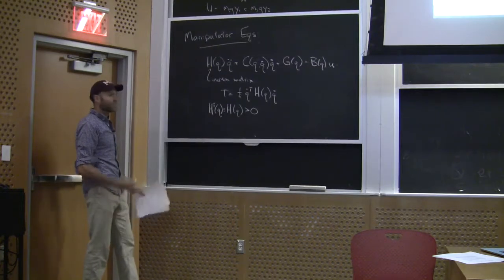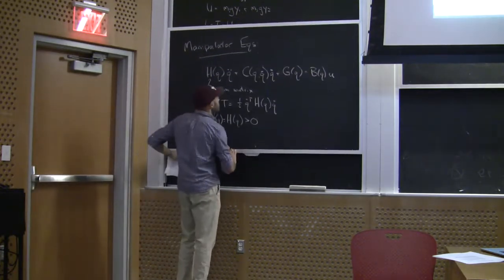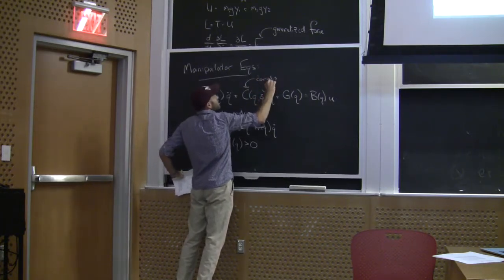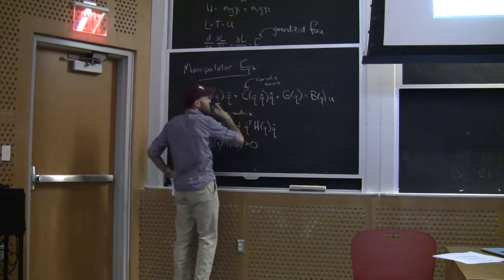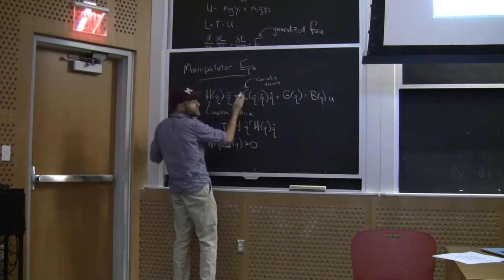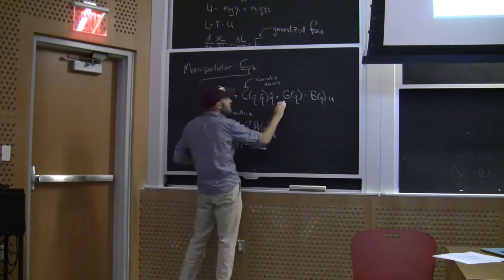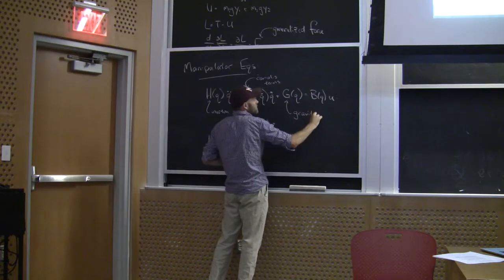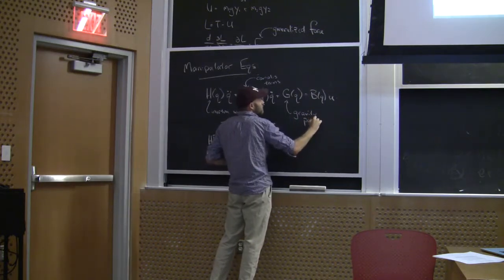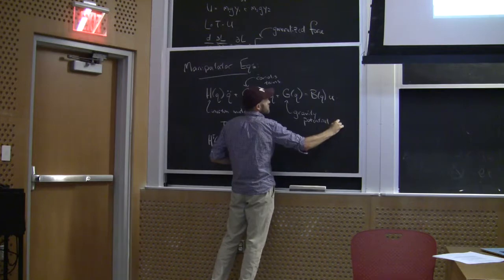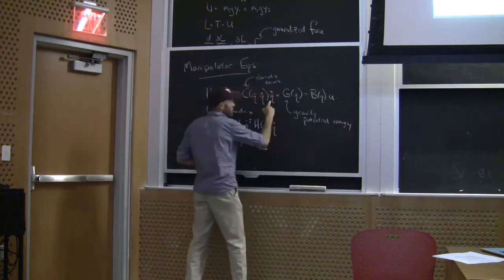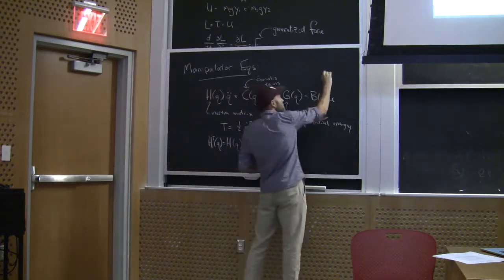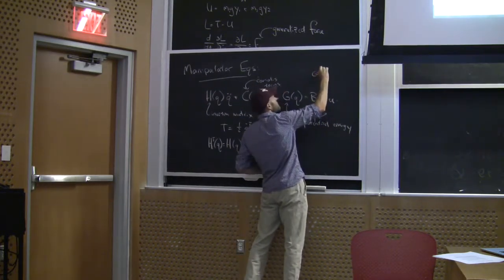Okay? And it's just gobs of structure in these equations. This is the Coriolis terms, roughly speaking. It has structure, you know, H minus 2C is skew symmetric. There's all kinds of structure like this. This is roughly the potential, the gravity terms, that's why it's got a G. Terms from potential energy. These Coriolis terms always have a component in Q dot, and it's control affine.